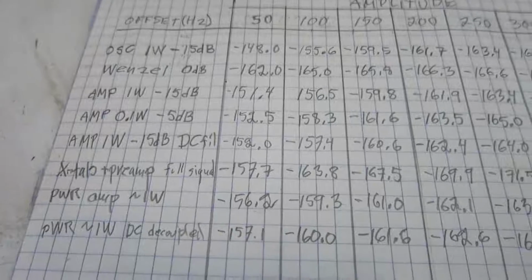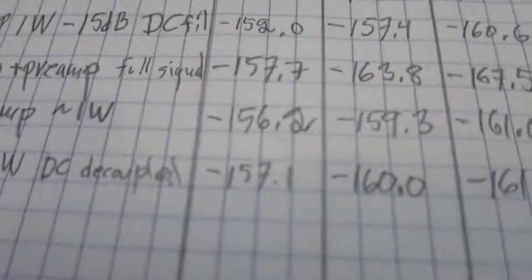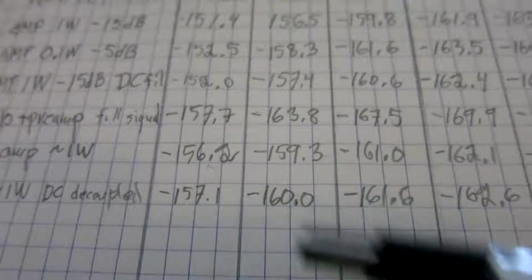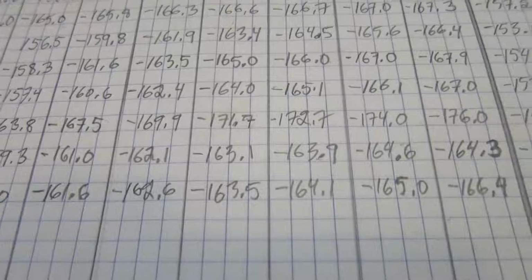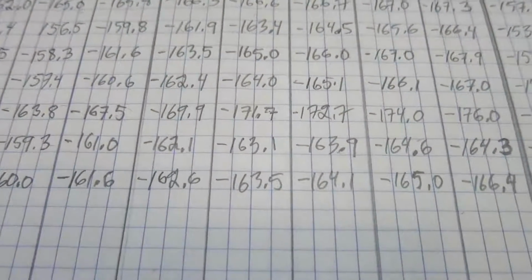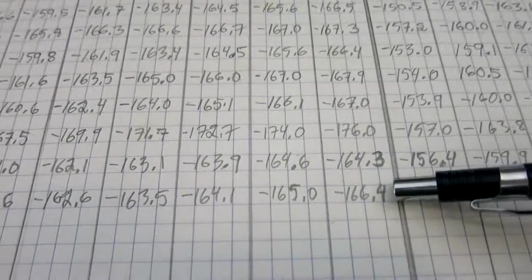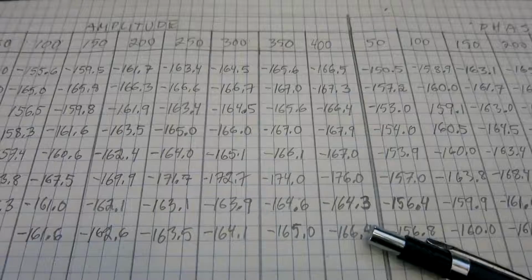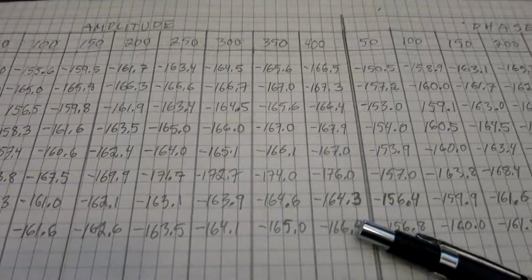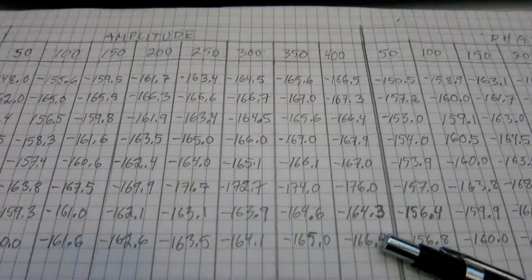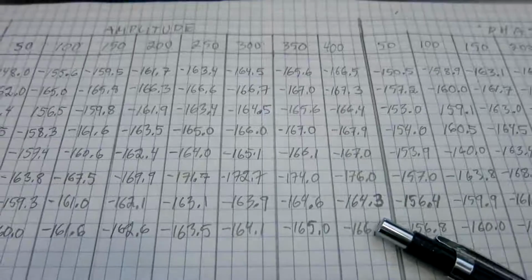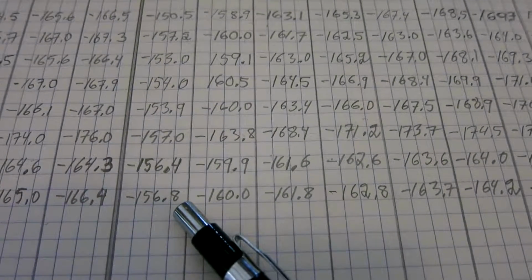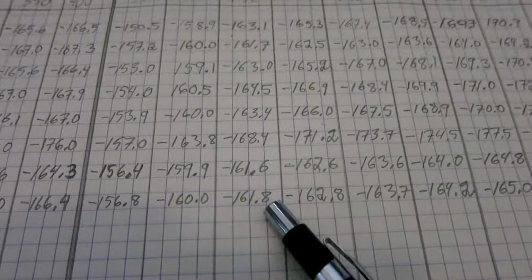noise. By filtering the DC on the input of the power amplifier, the improvement is about 1 decibel, a little bit below, 0.6 perhaps. And it's these two lines that show the difference. And it's about the same for all frequency separations. It looks a little bit larger here at 400 Hz, and that is probably because I have now collected many more averages, and at 400 Hz offset this makes perhaps a small difference. But I'm not sure on that. On the other hand, for the phase noise, the difference is much smaller, maybe insignificant, 0.2 decibels or 0.1 decibel.